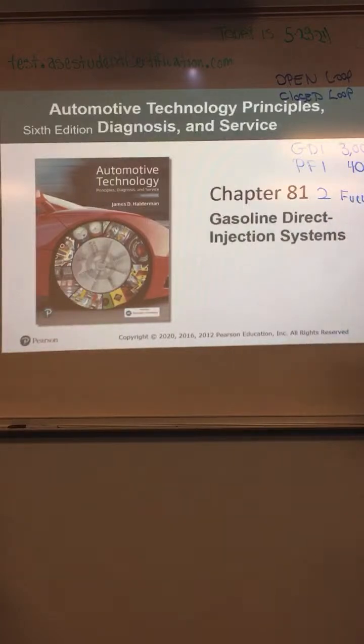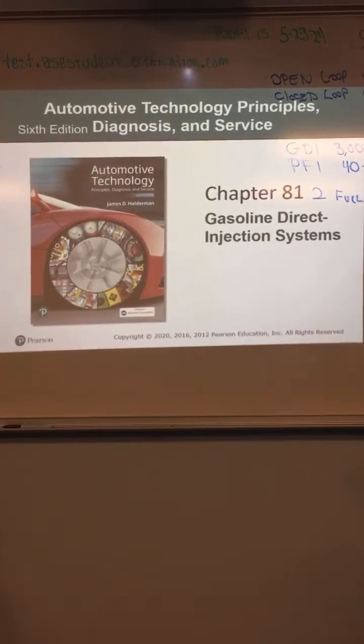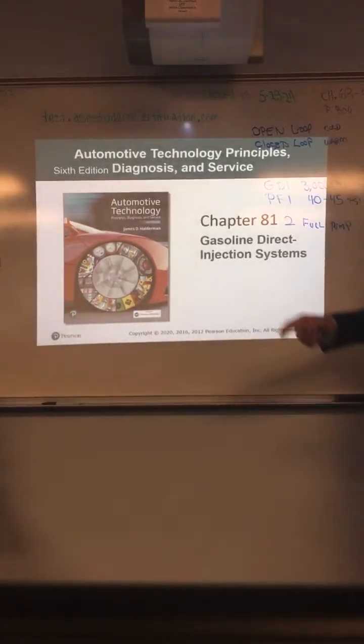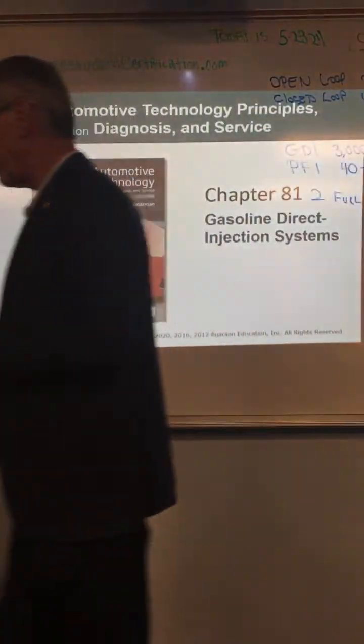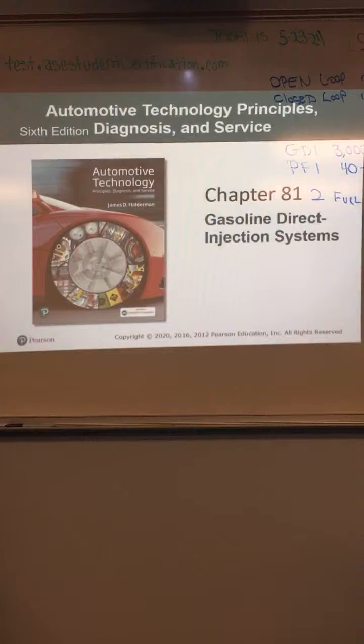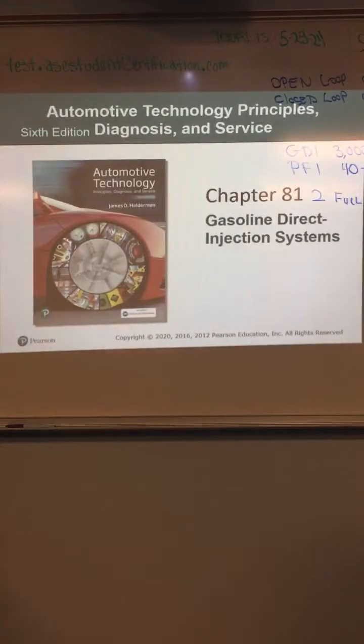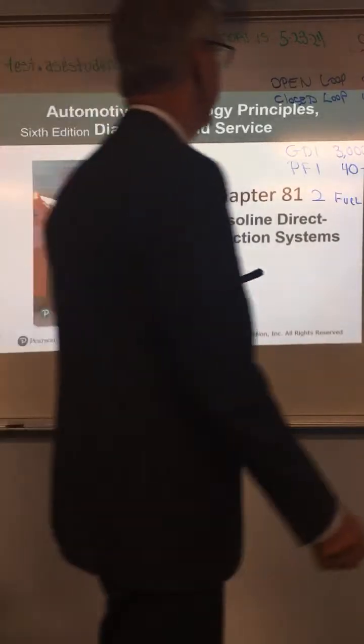It's gonna have an electric pump in the tank, just like all cars do. And it's gonna have a mechanical fuel pump driven off of the camshaft for the high pressure fuel pump. We've looked at this before. The oddball lobe on this cam is this one, right? This is the one that doesn't look like any of the other ones. This drives the high pressure fuel pump. This is the same cam that's in your Camaro. The high pressure fuel pump is driven off of this. That's what achieves the extremely high pressure, could be up to 3,000 pounds.